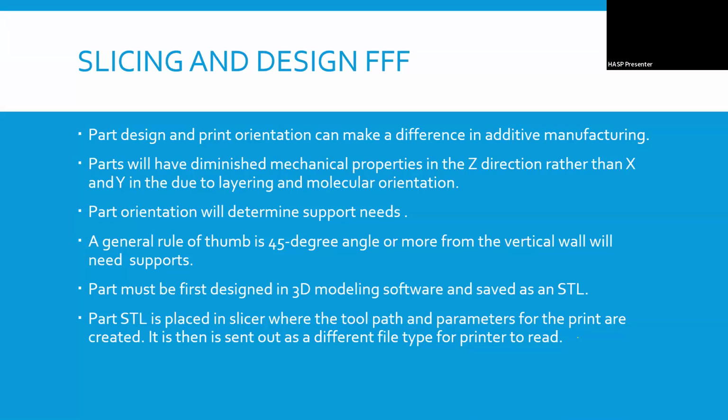So these cutouts right here, they're at 90 degrees to my vertical wall. So that's why they need supports. They need something to hold it up. So when you get over that 45-degree mark, you're going to need something to hold up the rest of that layer.